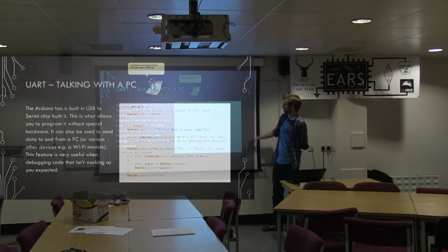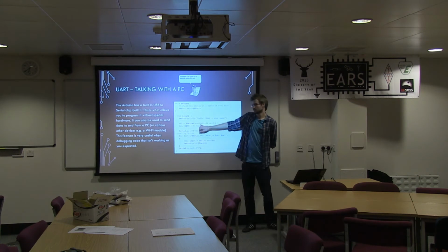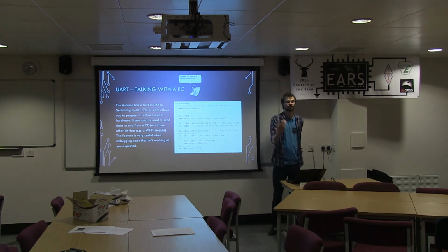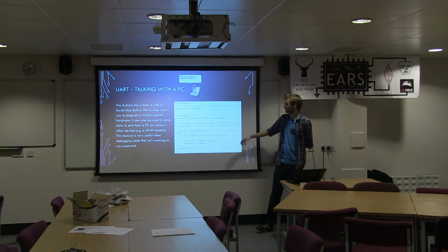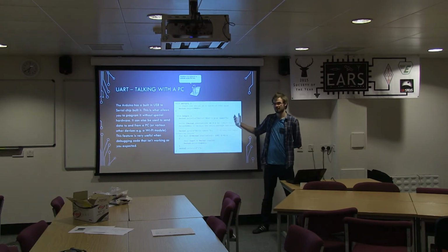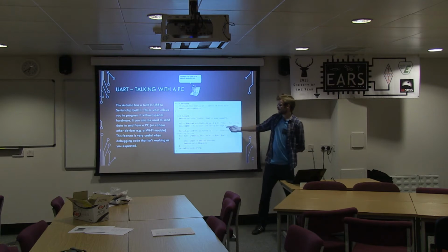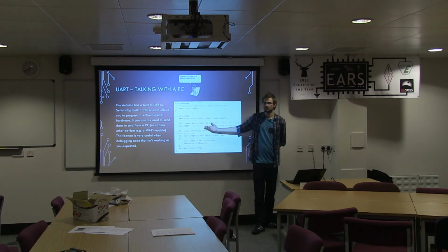Yeah, so this code carries on. You've got Serial.available, which will tell you simply if you have sent characters from your computer to the Arduino. If it's 0, there's none there. If it's anything above 0, that's how many characters it's actually read in. So this piece of code is just waiting for you to type something. There's a bit of a delay on this one, just to make sure you finish sending everything.